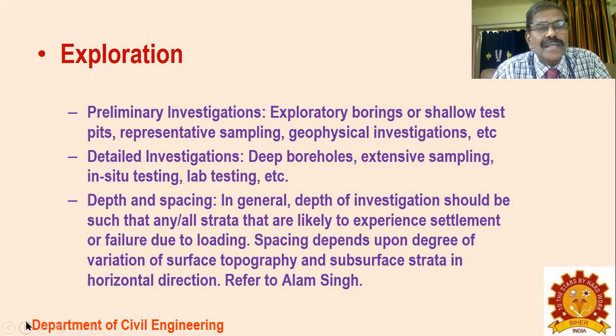Exploration. The preliminary investigation involves exploratory boring or shallow test pits, representative sampling, geophysical investigation, etc. Then detailed investigations are deep boreholes, extensive sampling, then in situ testing, lab testing, etc. They are the detailed investigation. They are very expensive and carefully done.